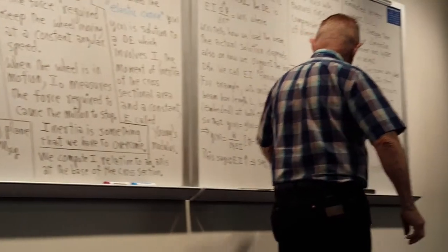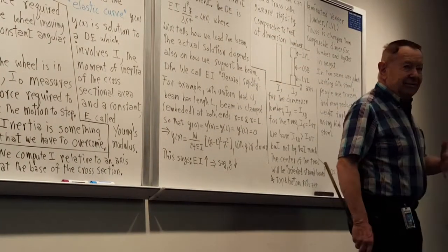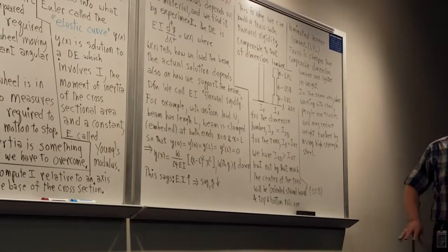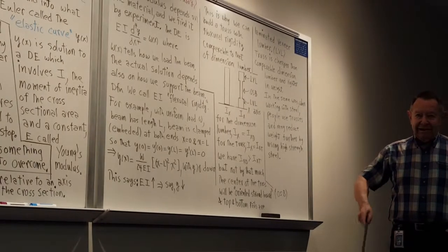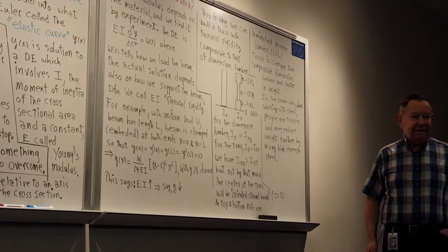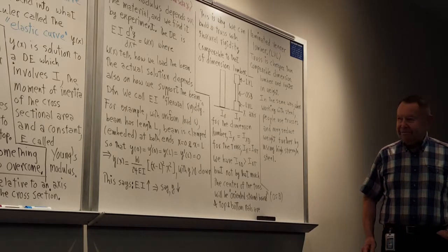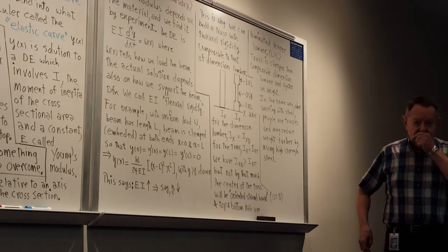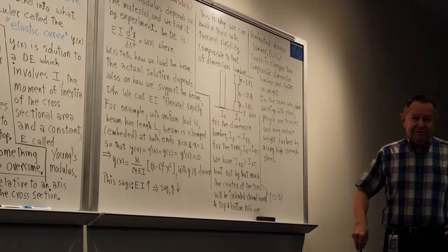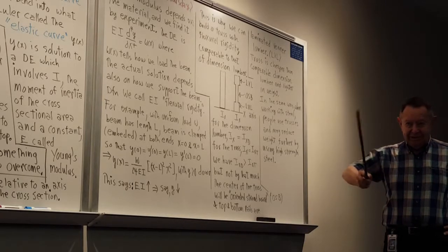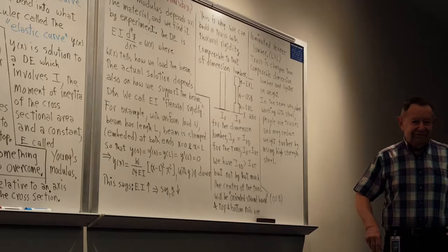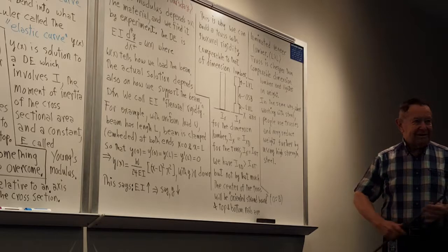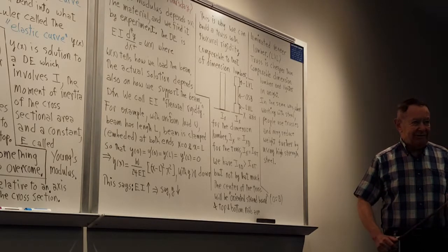So what you find is that compared with dimension lumber that would be comparable height and width to the rail, these have about as much strength, because of the very comparable moments of inertia, and they cost a lot less money than the corresponding dimension lumber would, if you can even get it, which is hard to do, especially that bigger one, because the trees now just aren't that big mostly.